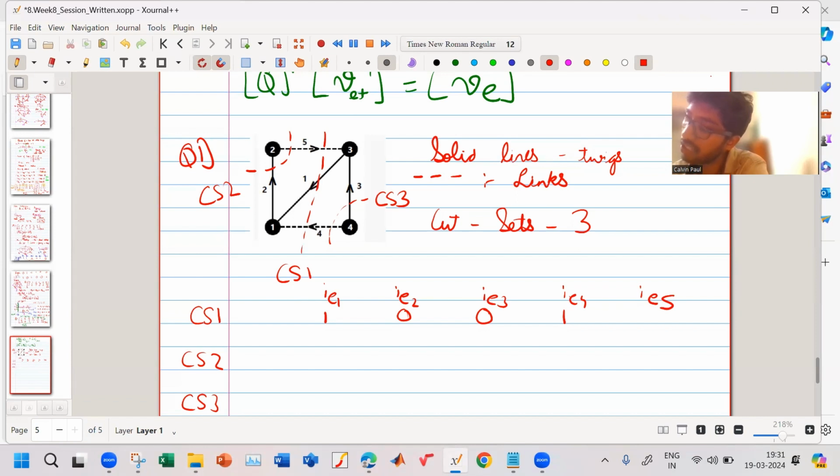If you see the arrow, it's going out of the cut set. Sir, if you take the part before the cut set, then it is incoming, so take incoming as positive 1. Then consider 5 as outgoing. So anyone can take before the cut set or after the cut set, left side or right side, any one side we can consider and choose the directions, incoming and outgoing.